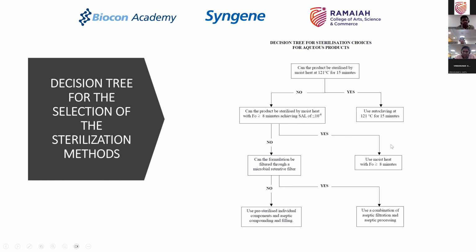Okay. Now, the third is, okay, I can't achieve it by doing this. Then, can the product be filtered through a microbial retentive filter? Can you just filter it and get rid of the bioburden? If the answer is no, then your decision making changes. If the answer is yes, then by using a combination of filtration and aseptic processing, you could go ahead with the process.